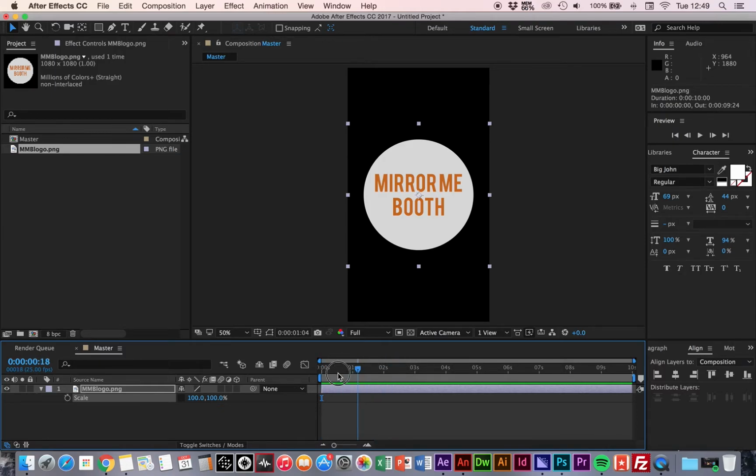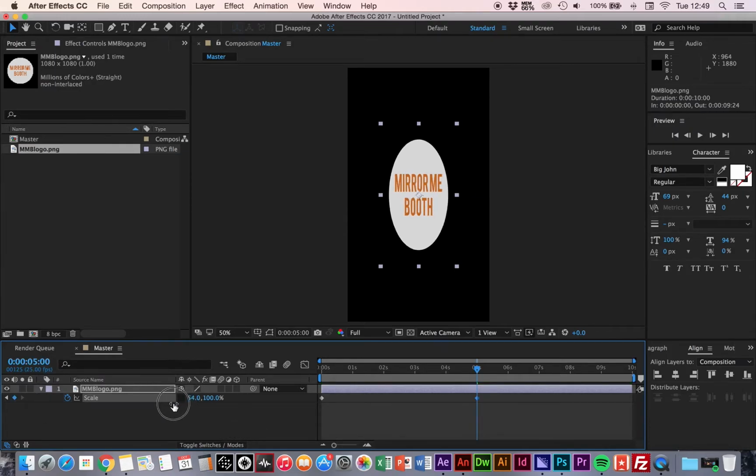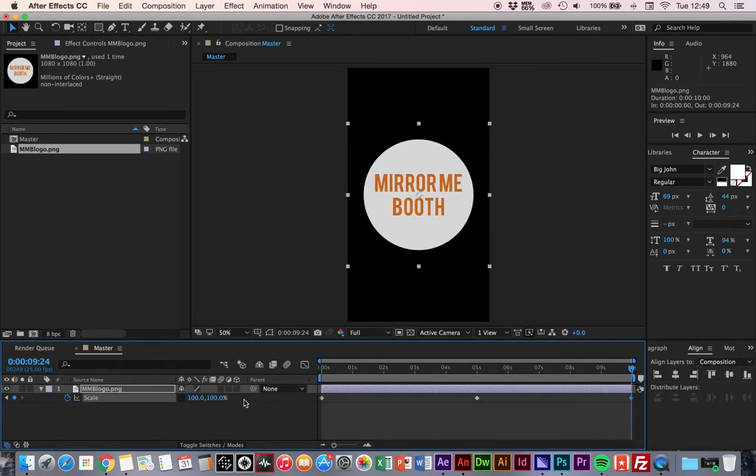So with the cursor at the 0 mark, press the little stopwatch next to scale in order to drop a keyframe there, which is at 100%. Then we're going to scrub along to the 5-second point. As you can see over here, we're at 5 seconds, and we're going to change the scale down to 0. And then we're going to scrub along to the 10-second mark, and we're going to scale it back up to 100%.